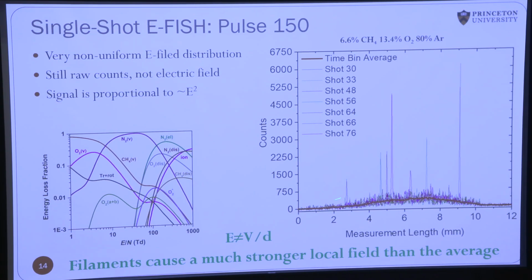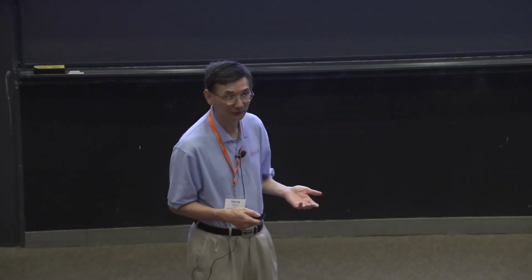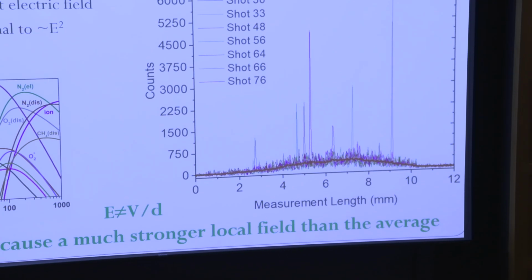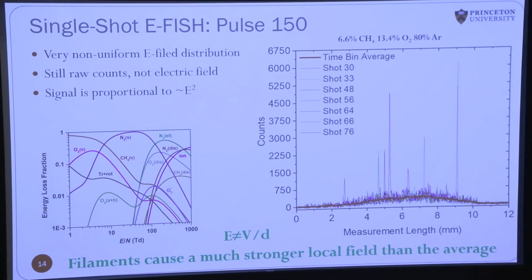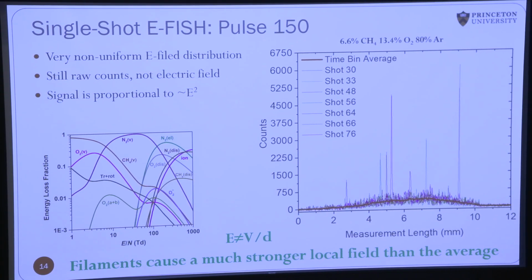So, for example, you can see that if you take a single shot of the plasma discharge between the electrodes, you can see a little spike. And each of these spikes is a clear indication that charge accumulates on the electrode, and that charge will create a streamer flying to the other electrode. I think that is a clear indication of how dielectric barrier discharges behave.